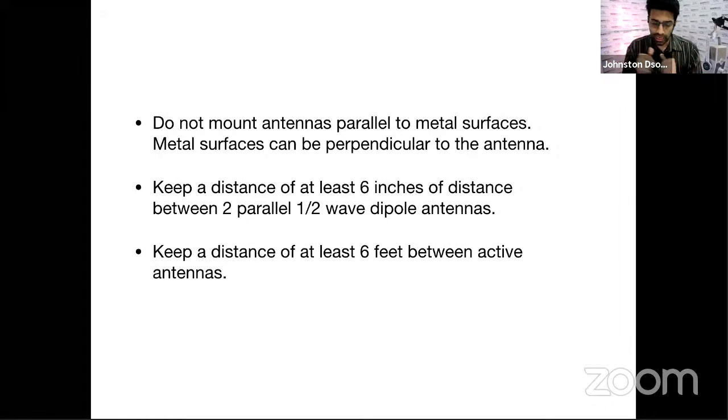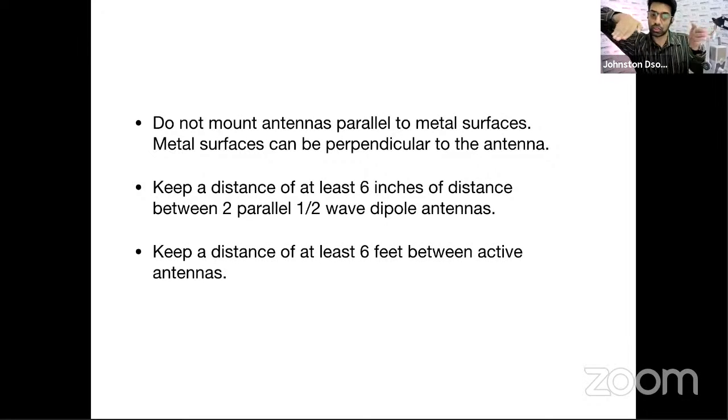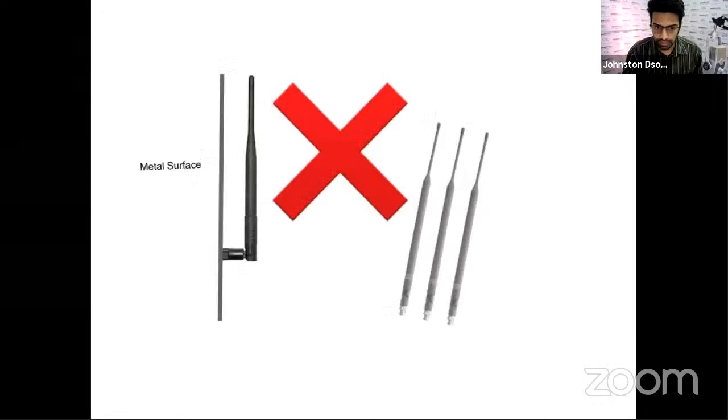each other. Now in a diversity system, when you have two antennas, both the antennas don't need to be in the same orientation. One antenna can be in the other orientation, so that you cover both the planes. For example, if your fish fin antenna is straight, the diversity antenna, that is the other antenna, can be put on the other side, so that if your transmitter or your receiver angle moves, it will be picked up by one of the antennas. Is it clear? Did you understand that?